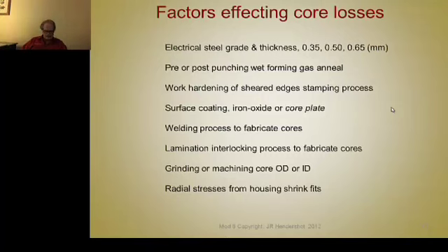core losses are. And we haven't proven what the true reason is yet, but we have a suspicion. We assume that the lams are all punched off of a die, and they're basically on those motors in succession. The die couldn't have worn much, so that the burrs didn't change much. So we conclude that whatever method is used to hold that stack together isn't repeatable from one to the other. And the most likely culprit is the clamping pressure.